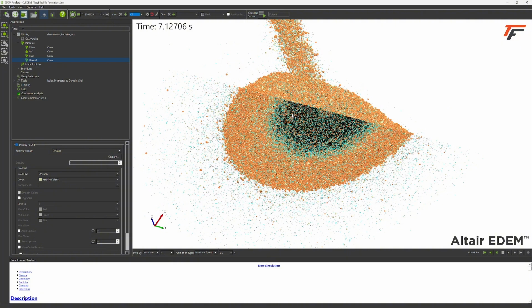And it's the opposite when you pile fill. You have the most amount of fines, the least amount of airflow, the highest chance for microbial activity, the densest layers. So the possibility of you opening those sumps and grain either not coming out or flowing for a little while and then not coming out is really high.